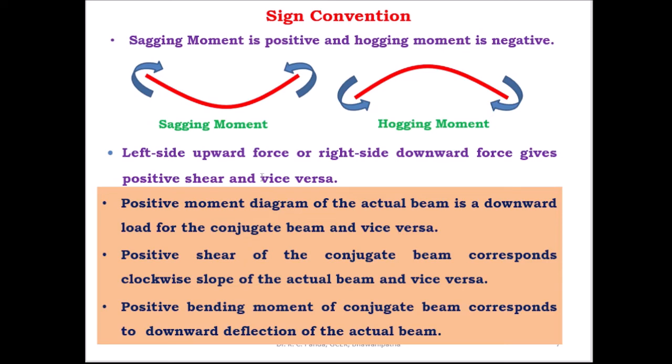The left side upward force or the right side downward force, you have to take as a positive shear, and the left side downward force and the right side upward force, you have to take as a negative shear.